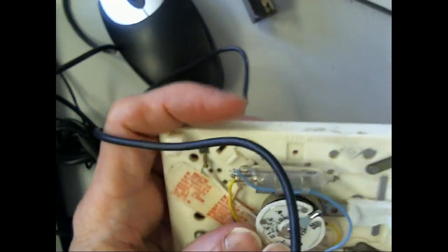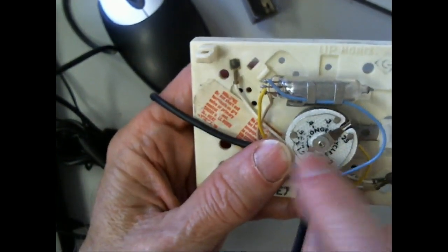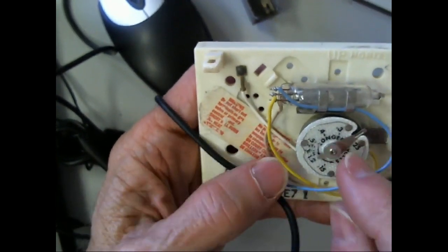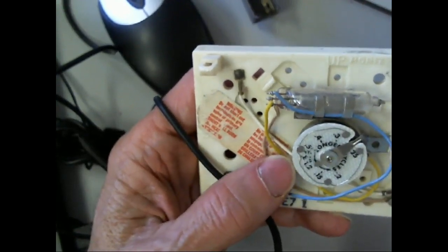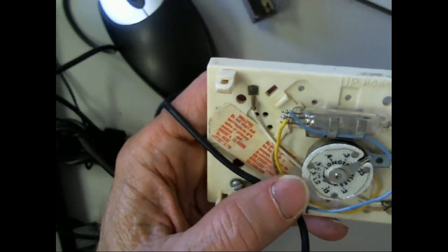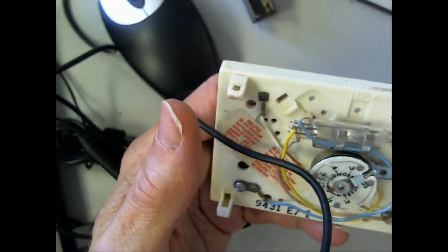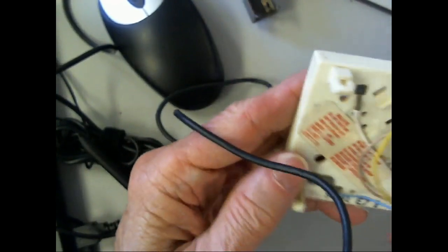And this is where you would calibrate it. So you'd come up here and you'd move this around. The person that set it up or built it would use this to calibrate it. So they'd put it up against a known temperature, and they'd set this until the switch, and then they'd set this at the same temperature and calibrate it so the bulb would move.